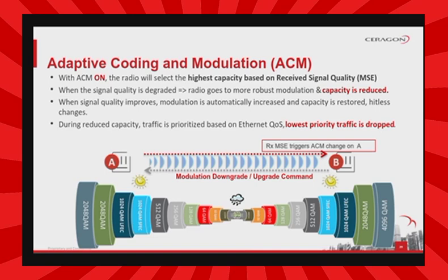The ACM mechanism can cope with 90 decibels per second fading in order to ensure the highest transmission quality. The ACM mechanism is designed to also work with the quality of service in each element, to ensure that high-priority voice and data frames are never dropped, thus maintaining even the most stringent service-level agreements. The hitless and errorless functionality of ACM has another major advantage in that it ensures that TCP/IP sessions do not time out. Without ACM, even interruptions as short as 50 milliseconds can lead to timeout of TCP/IP sessions, which are followed by a drastic throughput decrease while these sessions recover.